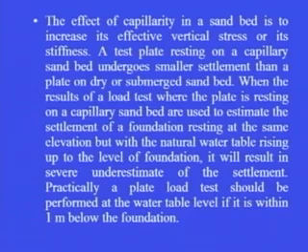The effect of capillarity in a sand bed is to increase its effective vertical stress or its stiffness. A test plate resting on a capillary sand bed undergoes smaller settlement than a plate on dry or submerged sand bed. When the results of a load test where the plate is resting on a capillary sand bed are used to estimate the settlement of a foundation resting at the same elevation, but with the natural water table rising up to the level of foundation, it will result in severe underestimate of the settlement.